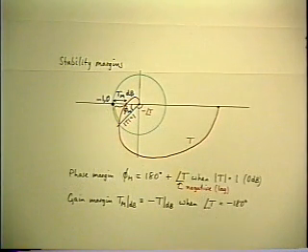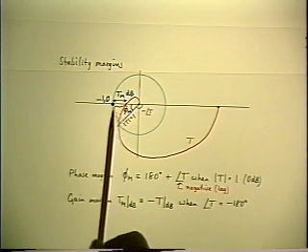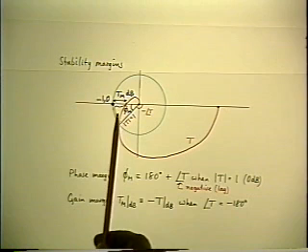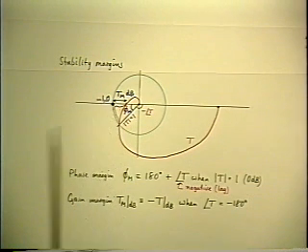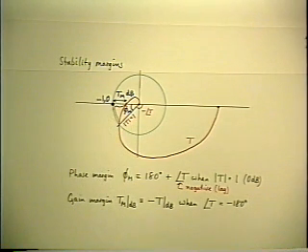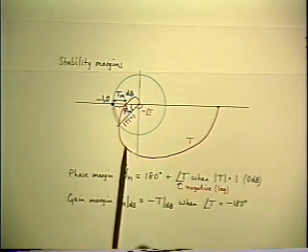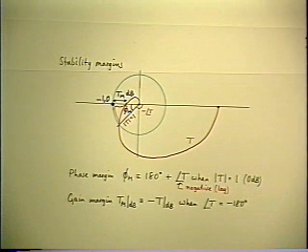It's stable. It has the same phase and gain margins as the original contour. But you certainly wouldn't consider it to be equally stable. Because obviously the closeness of the approach to the -1 point is of some concern. So those definitions of margins are not complete.